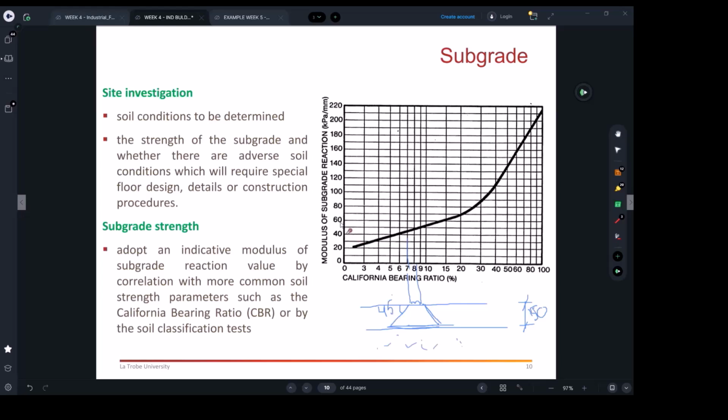So now what we're saying here, the soil engineer is telling us if you're going to put 65 kPa on that soil, it will be displaced by 1 millimeter, which is really acceptable. It's not a problem at all. Some standards will tell you don't go more than 5 millimeters. So here you're definitely okay with this. My example was 10 kilonewtons, which is a very small number. All right.